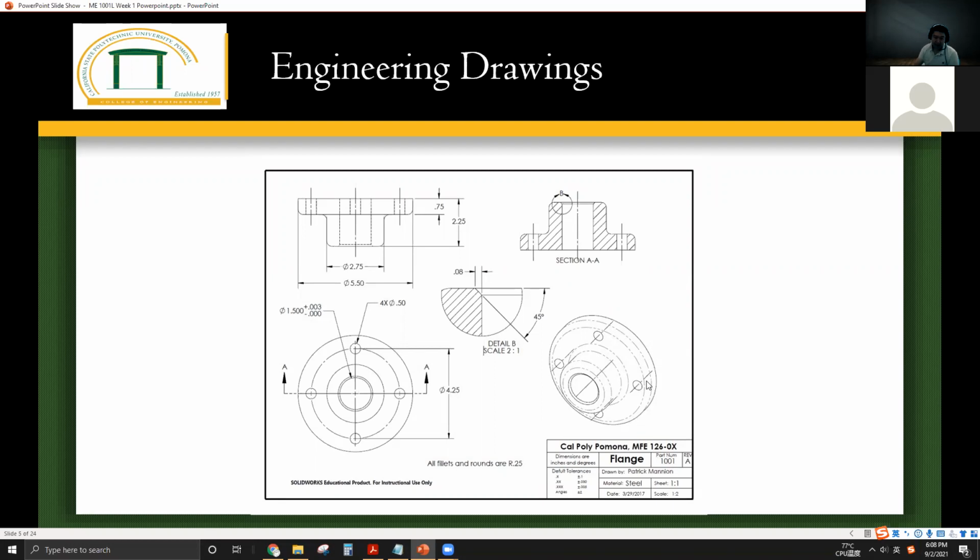Yep, everybody got the right answer. It's considered a fault. The reason is because the biggest it can go is 1.503. And same thing to the other side, the smallest it can go is 1.500. So pretty much the value on this dimension can only be 1.500, 1.501, 1.502, and 1.503, only those four values.